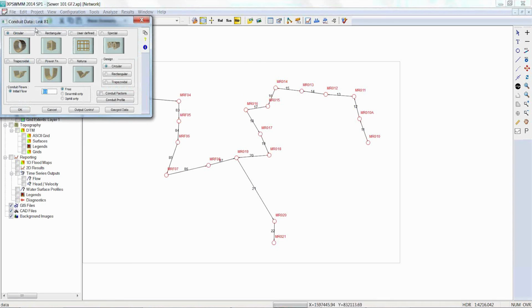At times, if you have a high-level overflow, we can look at what we refer to in XP as dual drainage, which means that the network could overflow to either an overland flow path or a road system at worst case. Hopefully your networks don't do that too often, but possibly only during a wet weather event or an extreme event. Nothing worse than having effluent in private property.